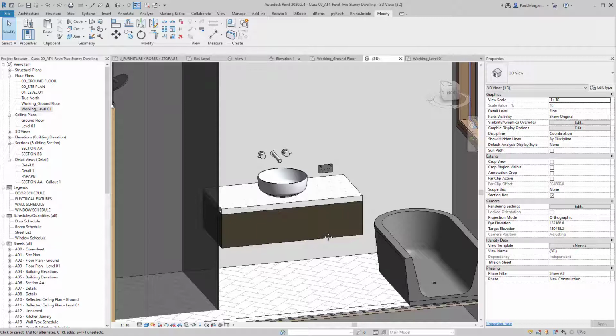And generally speaking, if you're going to edit a kitchen, you want to open up that kitchen by itself and then move everything around, because everything is sort of in relation to each other, all the appliances and white goods, and then close it, load it back into the family. The whole thing just updates at once. The other thing to consider as well is this is a single dwelling, so everything is really just a once-off. It's modeled in one location only. But if you're working in commercial or multi-res, you're going to have the same kitchen, the same bathrooms repeated multiple times. So again, the more you can put into a family, the more it means you just have to edit that one family, and it updates everywhere else.